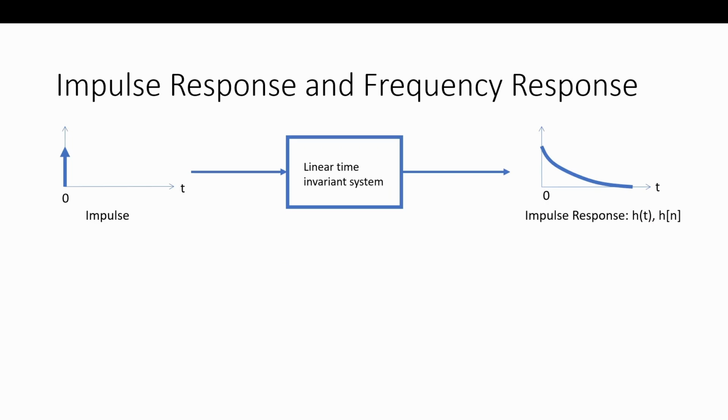So generally we have the impulse response and the frequency response, and we'll be describing these systems either in Laplace, as a continuous time system with the S-plane, using S, or the Z domain with the Z transfer function. So here, what do we see happening when we have an impulse? An impulse function in time is all frequencies in the frequency domain. So that's the Fourier transform of an impulse. We're changing instantly fast. It takes all frequencies to do that.